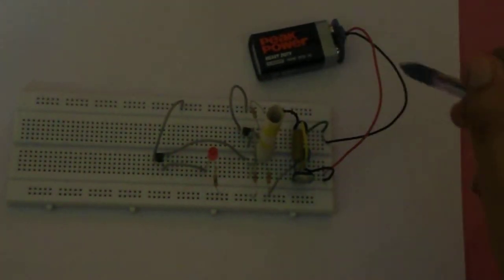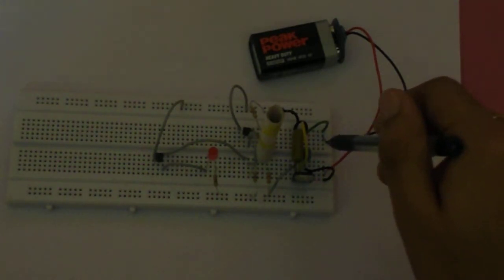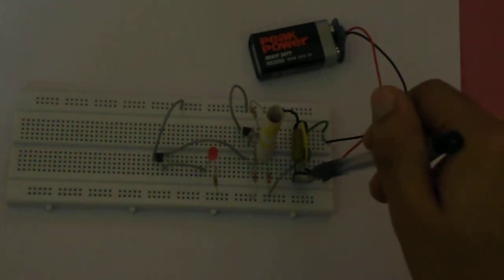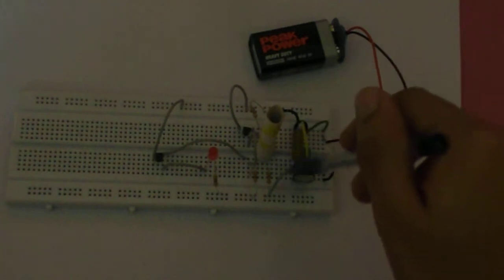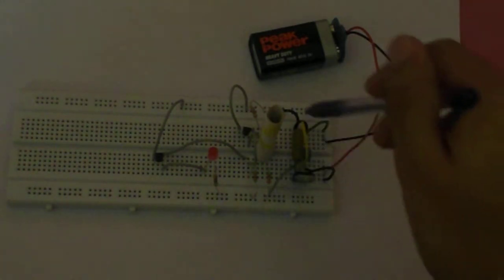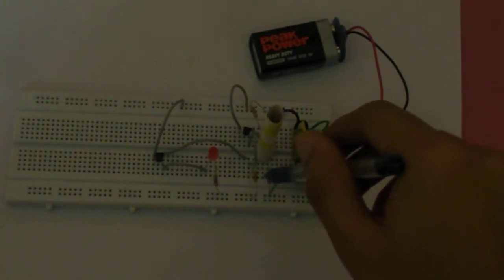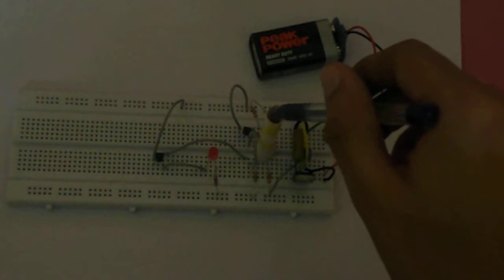So here we have the battery. It goes in there, the positive red and the negative black. This is the conversion portion. This is the LM7806 IC. The capacitors are over here. We get a 6 volt input over here and here. Then this is the 330 ohm resistor. Here we have the photoresistor.